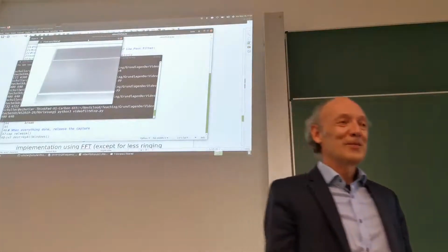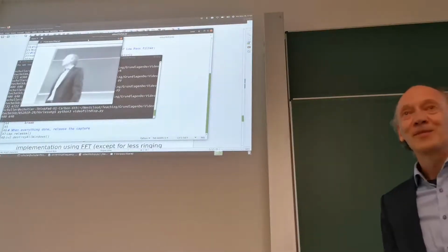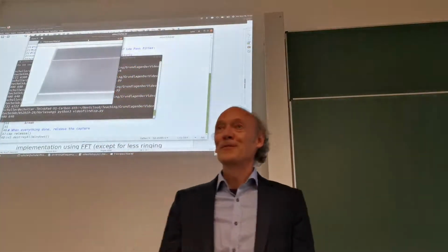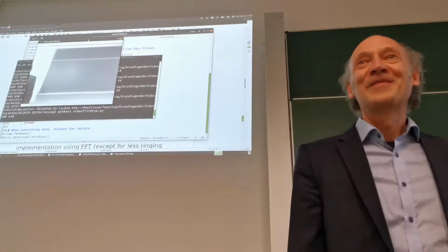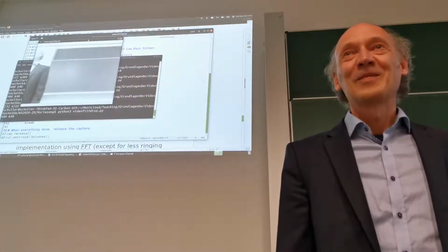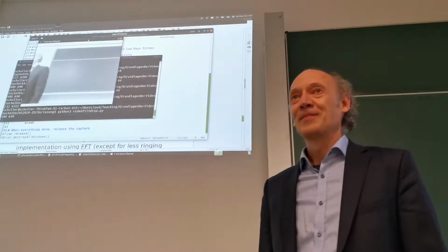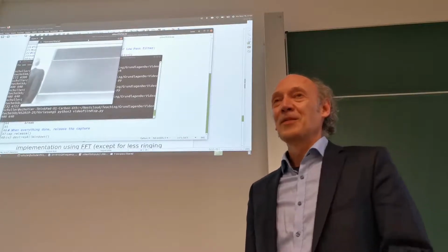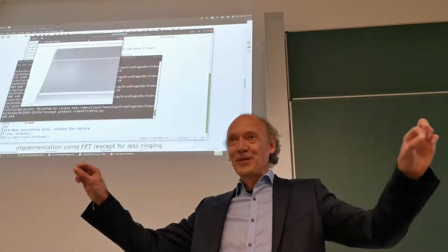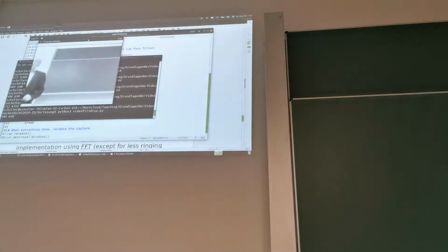But look at the ringing artifacts. What about the ringing artifacts? Do you still see ringing artifacts? No, they don't. Most of them are gone, there's something, but yeah. I suppose it has to do with we cut away the high frequency parts of the filter, so maybe it has to do with that. Yeah, actually we didn't cut the high frequency parts, but the ripples in the space domain. Right? So you're right, so that's actually the reason.